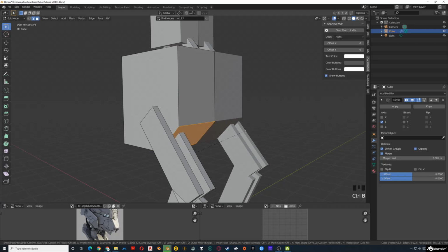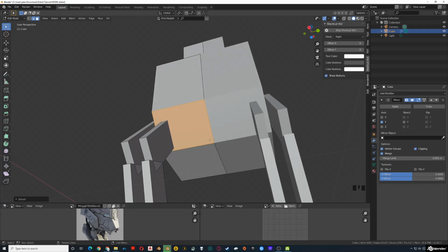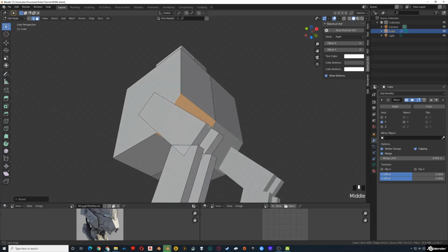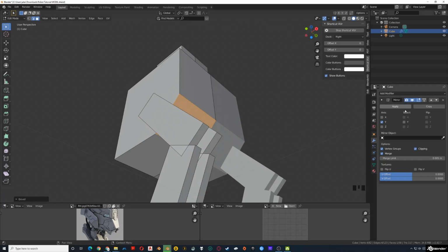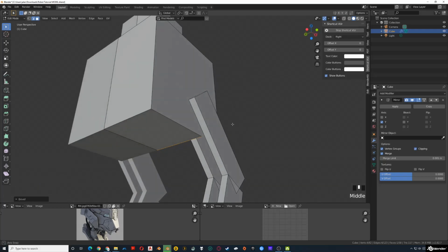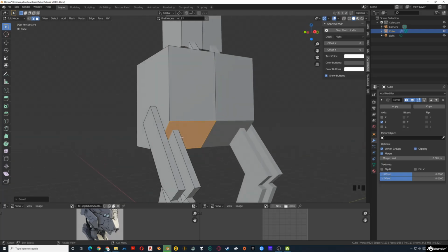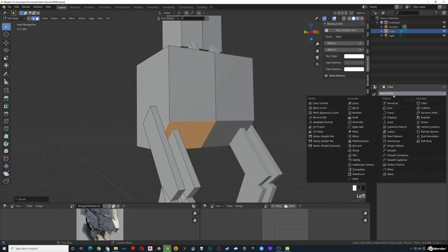And this is what's called a destructive bevel. The bevel cuts corners, and it's destructive because it doesn't add a modifier in your modifier list, which is useful, especially if you're getting ideas out of your head, but you can't go back later and modify it or edit it like you could if you did it in your modifier list.